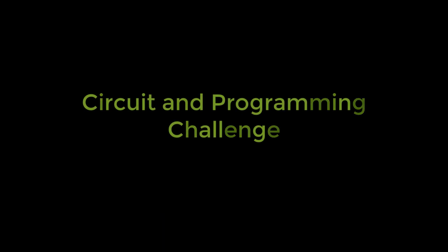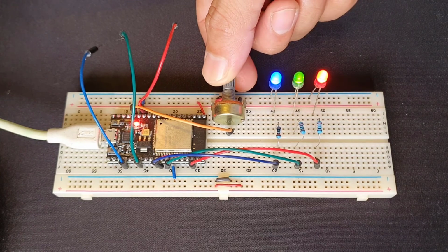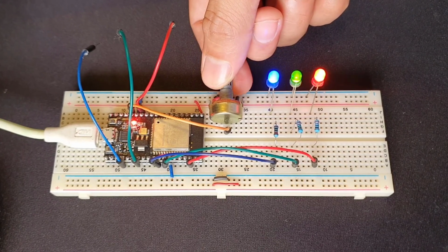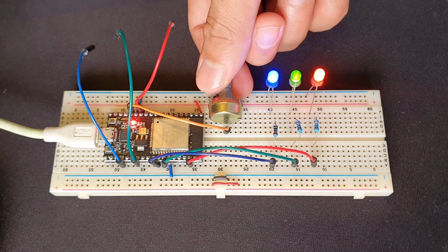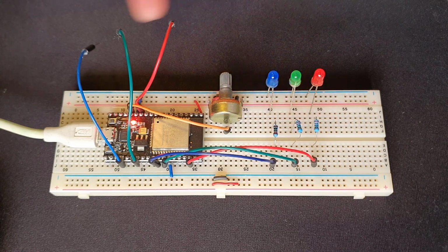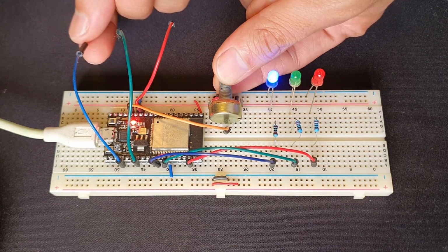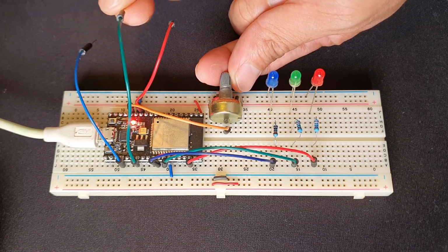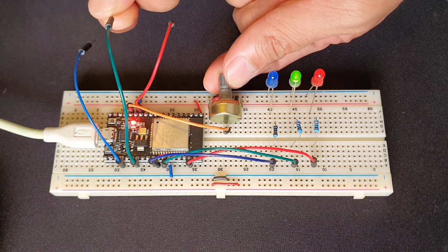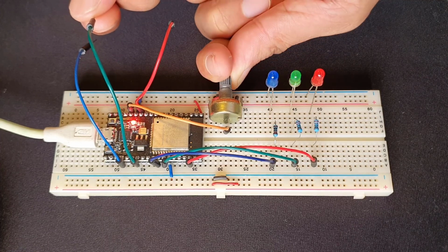And for your circuit connection and programming challenge, I want you to implement a similar circuit but using different GPIO pins. Same as with the example, the three LEDs glow and fade in sync with the potentiometer's knob rotation. Now, the three hanging wires will act as a selector to the three LEDs, wherein if the blue wire is touched, only the blue LED can be controlled. However, if the green wire is touched, only the green LED can be controlled. And the same goes with the red wire.